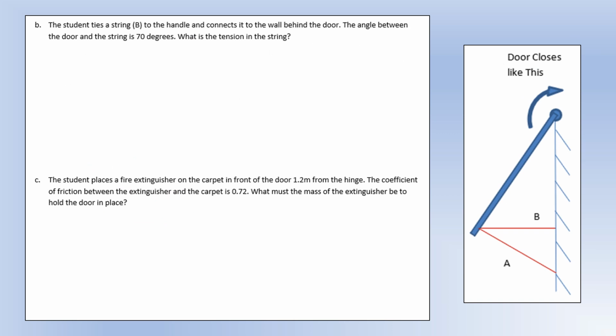Okay, so for the second example, the force and the 1.5 distance are no longer perpendicular. So what you do here is the perpendicular distance between the tension and the pivot is now going to be 1.5 cosine 20, or we could have done sine of 70, it doesn't matter. But we still know that's equal to the torque from the closing mechanism of 100, but this time, because the distance is smaller, we need a slightly bigger tension force.